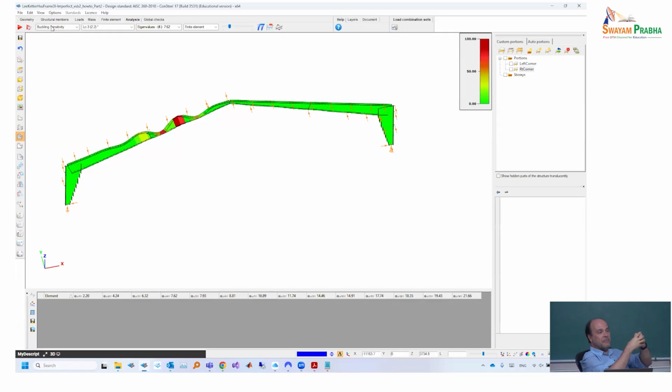What is important is the distribution of this energy over the structure. Because we say that those parts of the structure where there is visibly a high concentration of this energy are probably the relevant parts, and those where the energy from this given mode is very little are probably not relevant. We scan through the whole structure, and for each finite element we calculate the deformation energy. We find the biggest number, and we scale this value up to 100%. This will be the maximum.